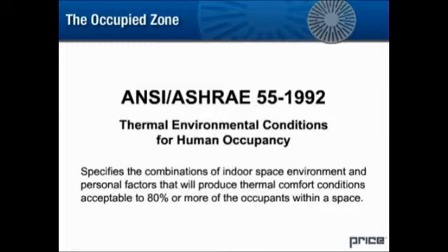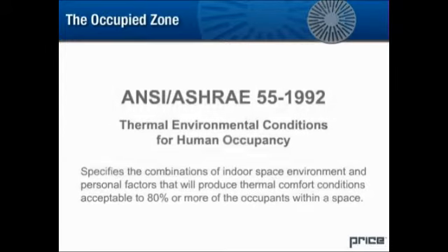Thermal environmental conditions for human occupancy specifies the combination of indoor space environment and personal factors that will produce thermal comfort conditions acceptable to 80% or more of the occupants within a space.